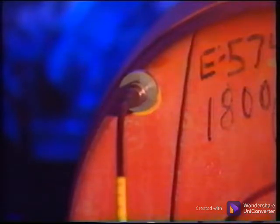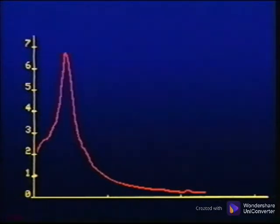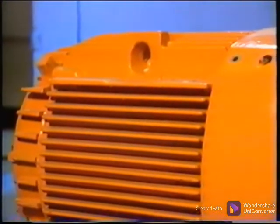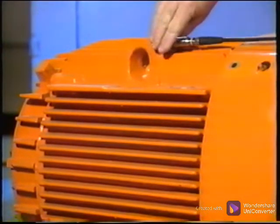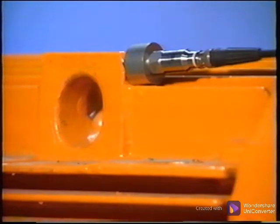Be sure the bolt is tight. Long bolts may have resonant frequencies that substantially reduce the linear response range of the sensor. Another usable location is the lift hook. If the lift hook is simply a loop, be sure to make the measurement at the base of the hook. If the lift hook is an integral part of the housing and of substantial size, it could be used and still obtain reliable data. Be sure the sensor is pointed in the true axial direction.